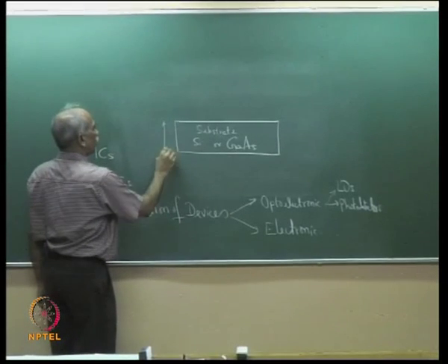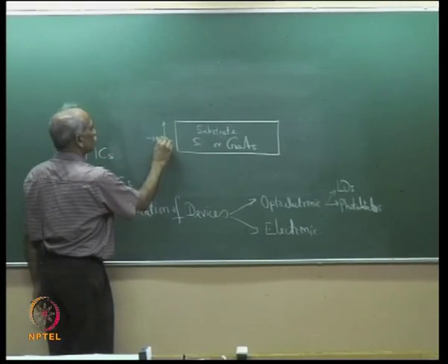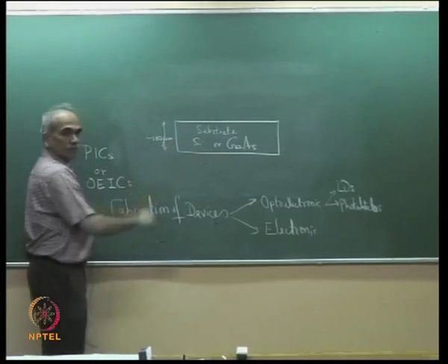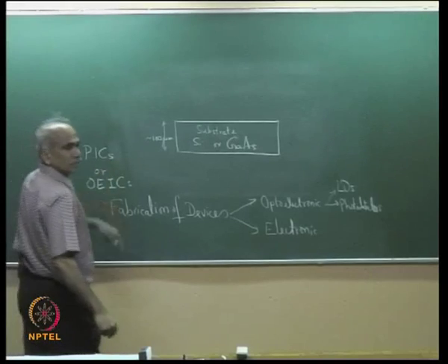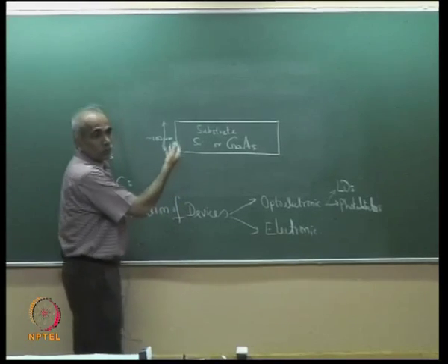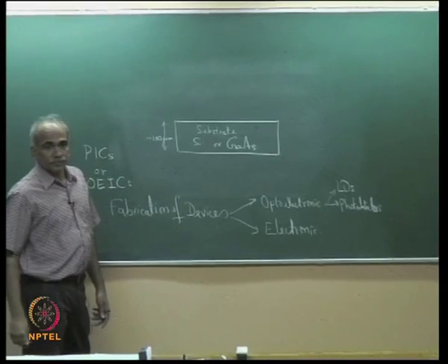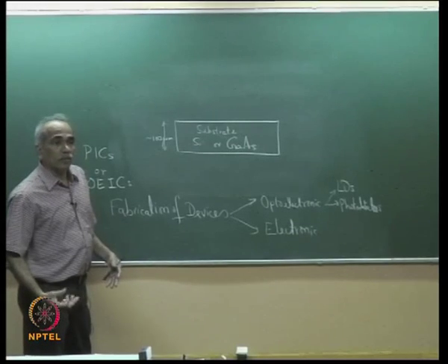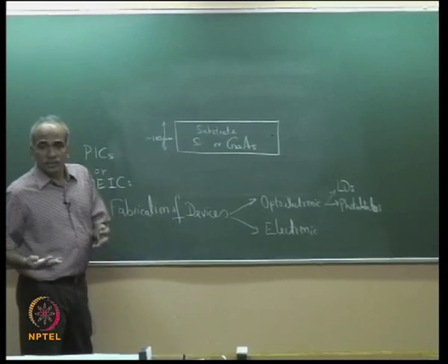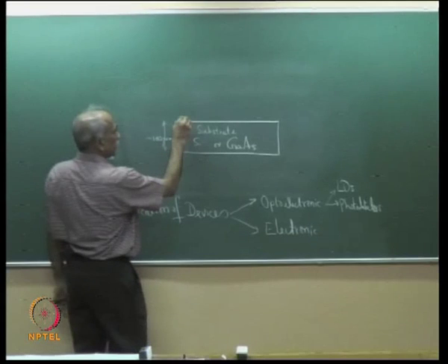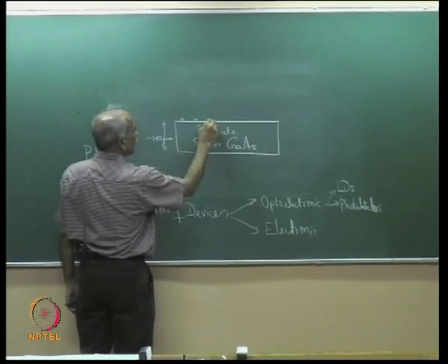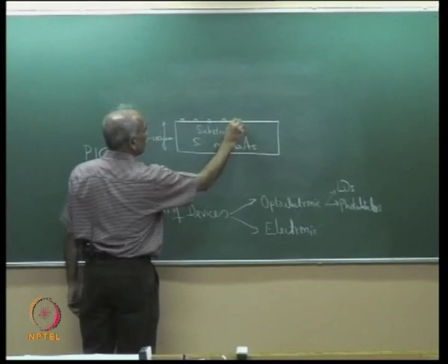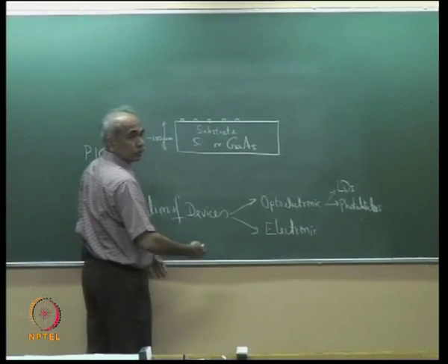Typically about 60 to 100 micron thickness. Dimensions depend. Typically, on this you grow a large number of components. Most of the electronic components which involve a p-n junction, you can deposit the required p-type or n-type dopant and diffuse.